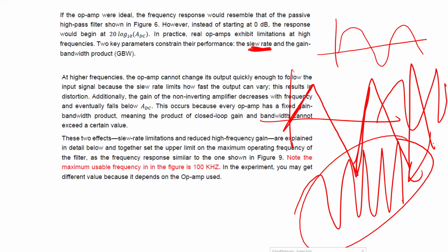This is because of the op amp. Again, guys, this can be a problem or may not be a problem. If you want to use the op amp before this frequency, it's not a problem. I don't care about it. If you need a higher frequency, you need to buy a more advanced op amp, or one that has high performance.